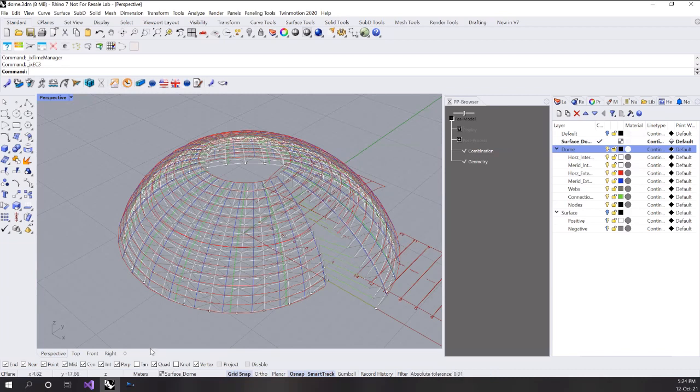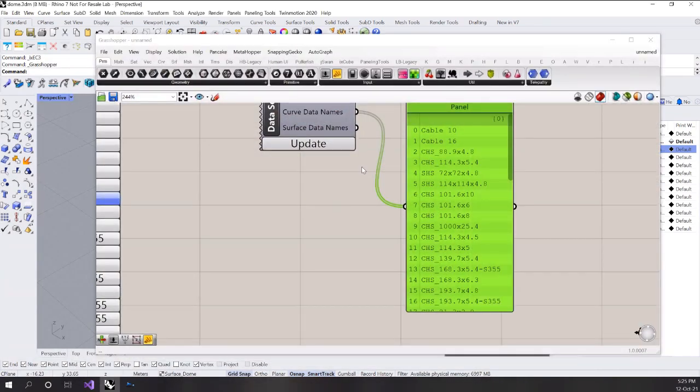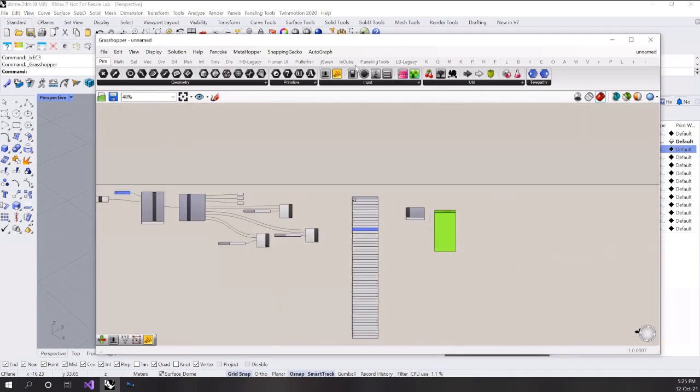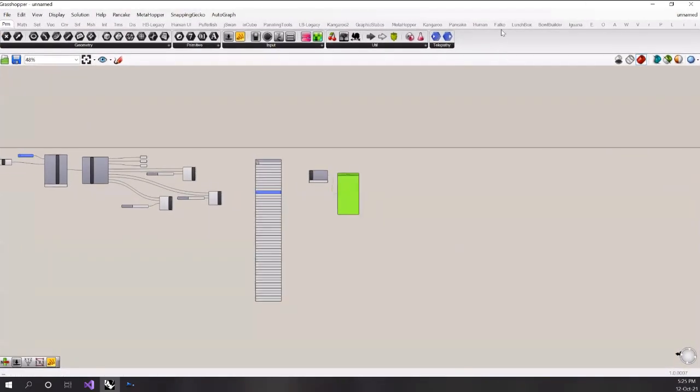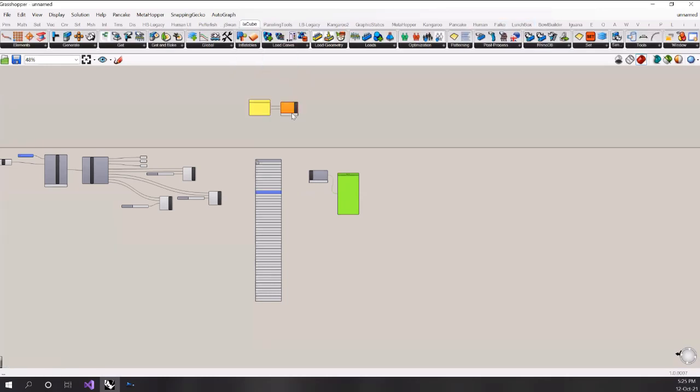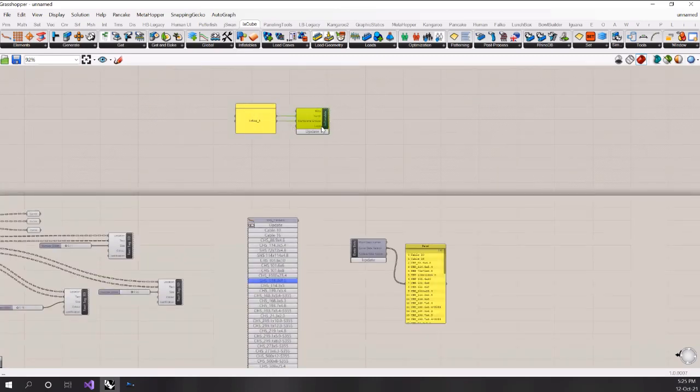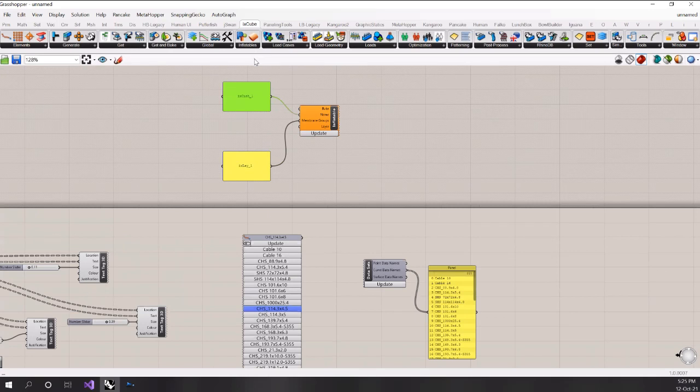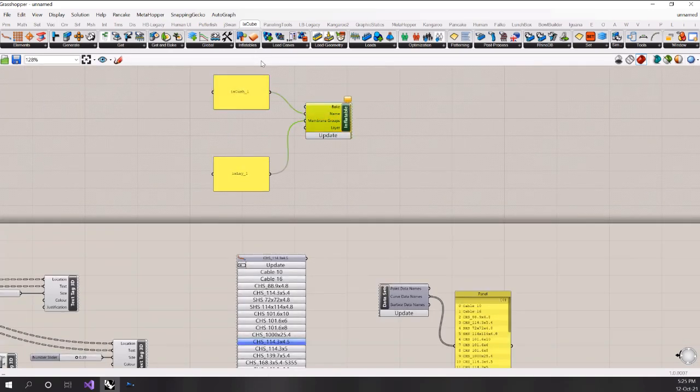Great. Another question was, would it be possible also to do pneumatic form finding? Yeah, falko? Absolutely. Yeah, of course you can. I didn't show you, but we can generate both from falko, and even from Ixcube, we can generate inflatables. So we can generate inflatables, and we can then define the chamber pressure for the inflatables, and then run the form finding. Next time I will show something a bit more complex.